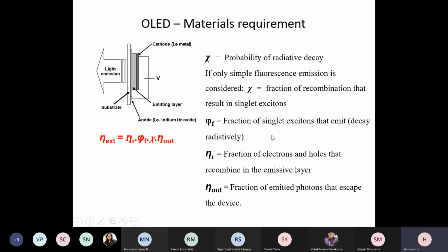When coming to charge carrier recombination, there are non-radiative processes as well. So there can be events of combination of electrons and holes that do not give rise to radiation. And that's why you have this factor, which is a fraction. It is not going to be one. It's not going to be perfectly one. And what fraction of that further is actually emitting radiation.